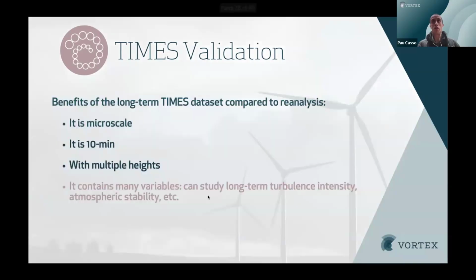And also something that we cannot forget, and is very new in these products, is we have the ability to check the standard deviation on a 10-minute scale. This is relevant because you can really plot the turbulence intensity, which can become very useful for offshore, for example, when there is a very, I would say, scarce availability of measurements from lidars, where turbulence is not very well measured, and met masts are not very affordable in offshore.